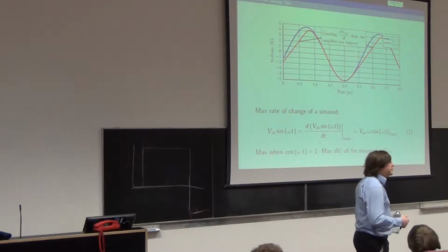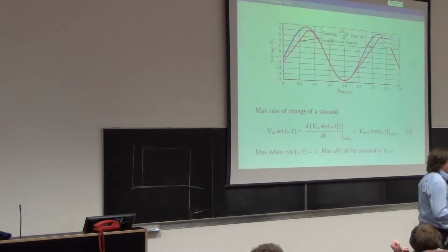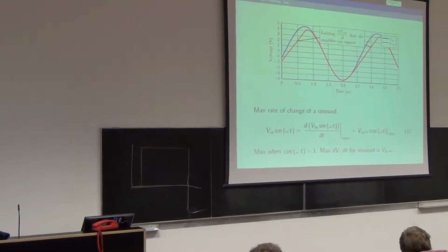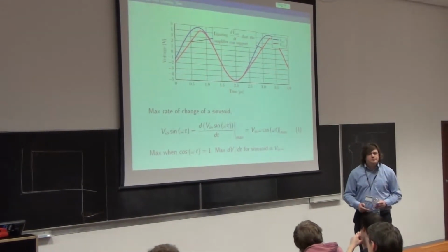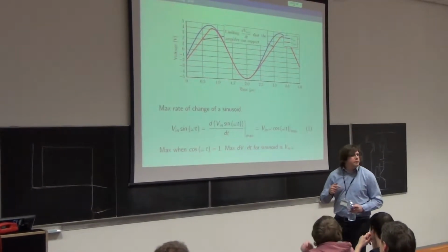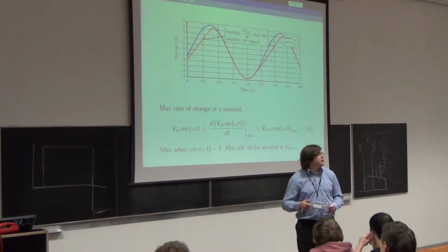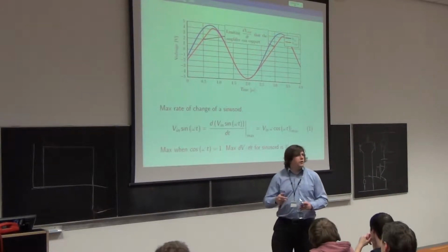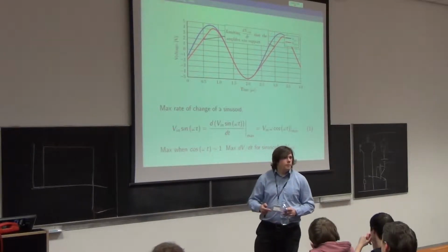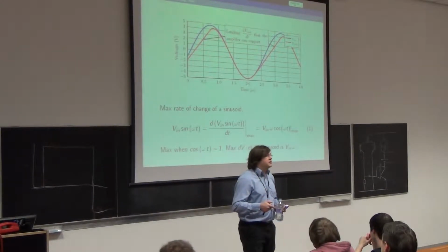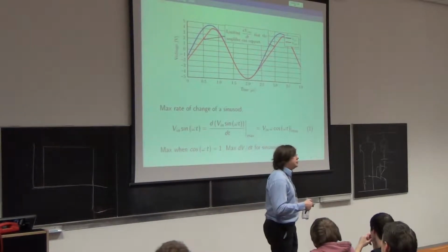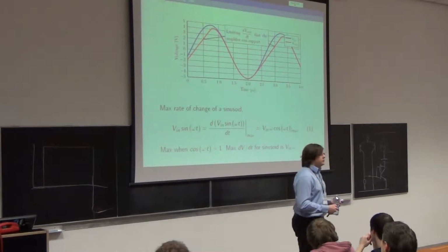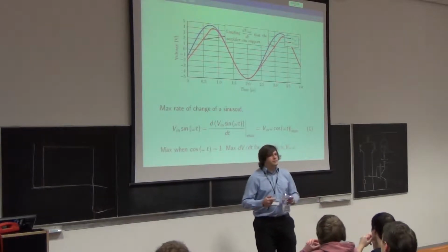Sometimes you will see written in the data sheet maximum power bandwidth, and that is another way of defining the slew rate. It's a bit iffy though. What it really means is, if you have the output signal voltage you need to deliver the rated power into a particular resistor, or load that they specify, you can get to this frequency, the maximum power bandwidth number, and you won't get slewing distortion. After that, you will. So it's really another way of defining the slew rate, but in looser terms.